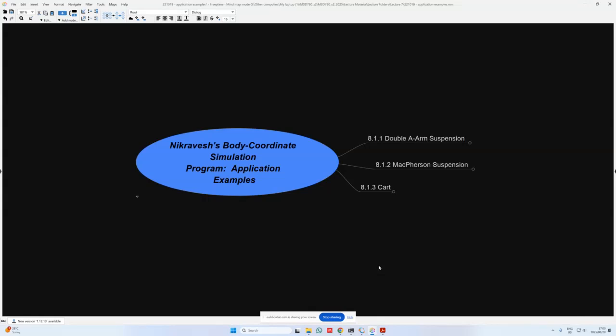A suspension system envelops a lot of the properties of point-to-point forces, the way in which we have to define the springs and the dampers, as well as some more complex joints, revolute joints, translational joints, those kind of things, how we can set them up and what their involvement is within the suspension system. We also looked at the AA arm suspension system firstly, and this was just a basic layout of a point-to-point force with some stock standard revolute joints that we wanted to specify on the system.